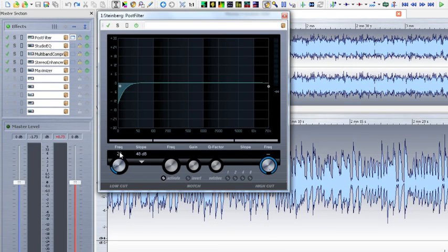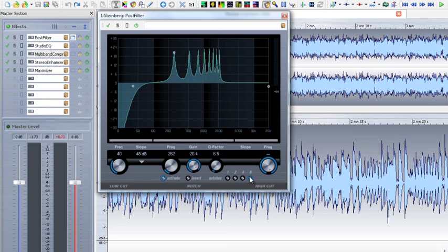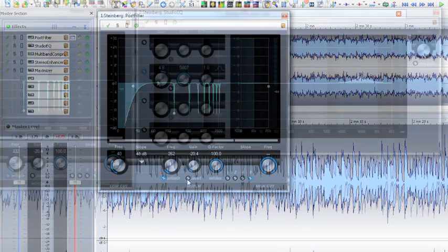Wavelab 7 also features many plugins taken from our post-production software, Nuendo. There's the Post filter, which we use here as a low-cut filter to reduce lower frequencies, such as footfall sound. The Post filter can also be used to remove interfering frequencies and their overtones. This is only possible due to its very steep broadband filter when combined with the invert function.